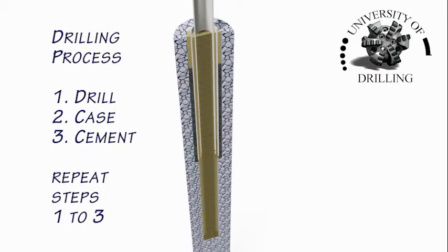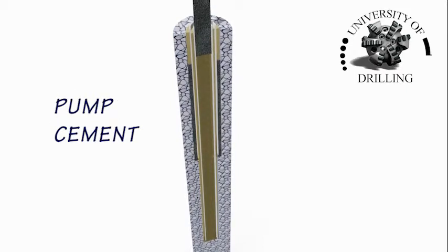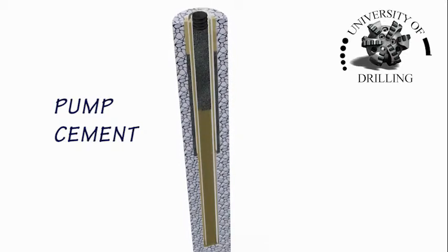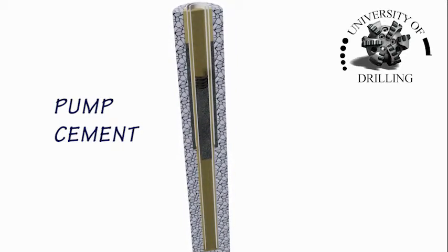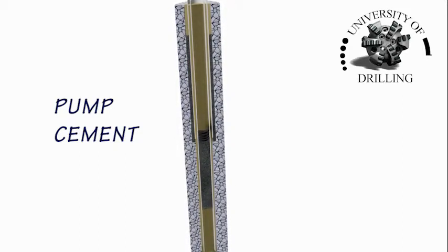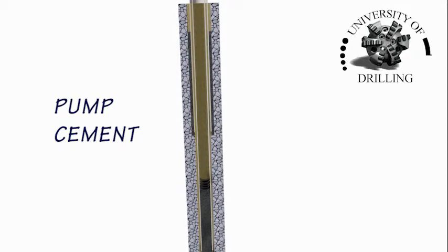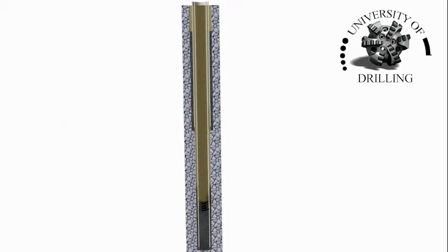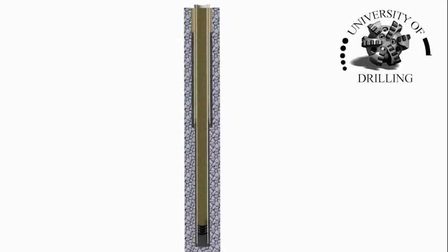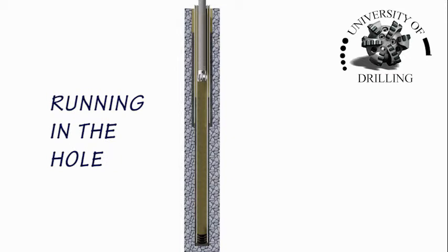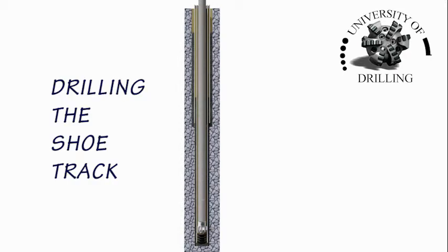Accordingly, the process of first drilling, then casing, and finally cementing is repeated over and over again to protect the surface and underground environments, using ever heavier drilling mud and smaller drill string and casing diameters until the well's total depth, or well TD, is reached. As you can see, the basics of drilling are relatively simple. Using heavier drilling mud, you drill new hole, run casing, and cement the casing in place over and over again until the final well TD is reached.